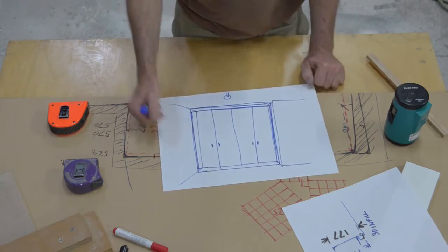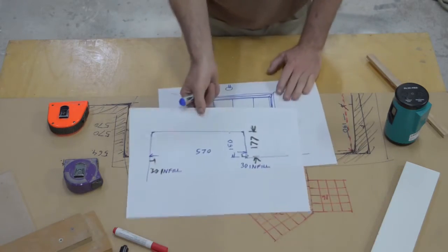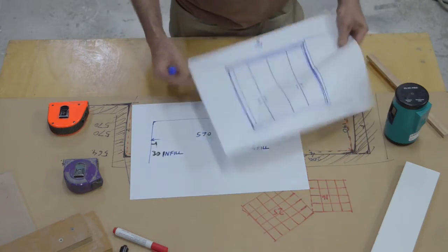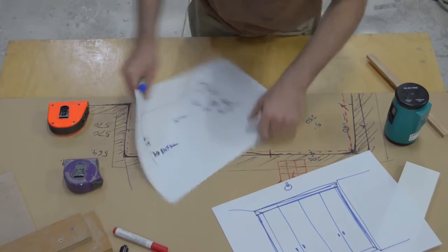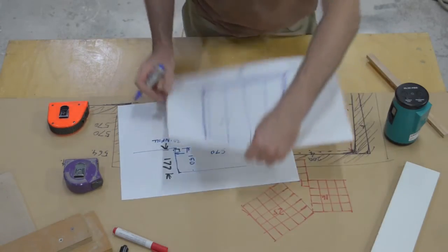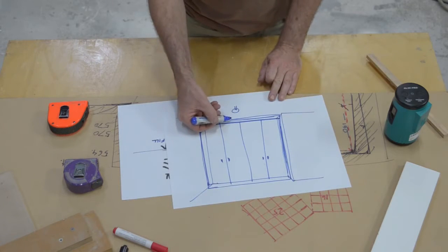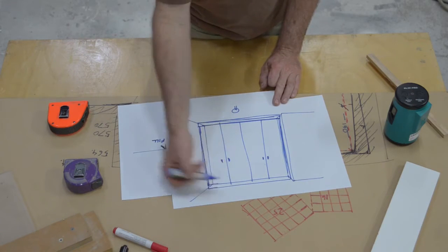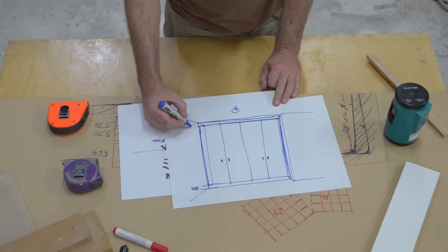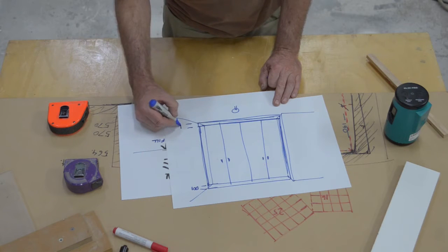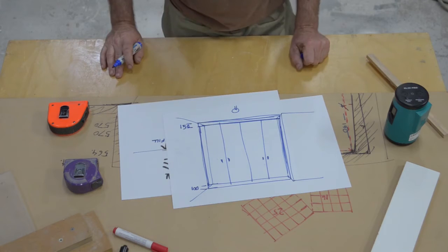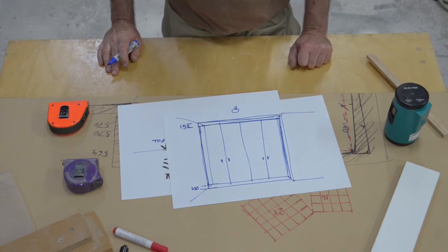That's our intended design. That's the facsimile of the width and depth. The height, I'm just going to throw in that it's a ceiling height of say 2400. But again, going back to the original design here, we have a bulkhead on the top side, we have a kick on the floor, and they might be both normally 100 millimeters or 4 inches or something like that, depending on where you're from and what measurements you take. I might even have this as 150. That gives me some tolerance to work around the ceiling and floor errors and so forth.